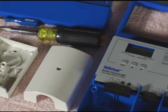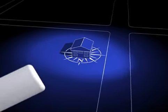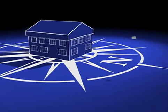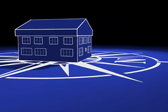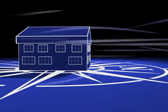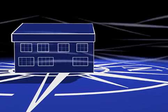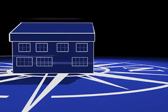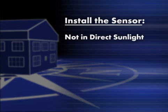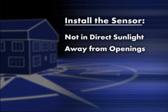Step 2. Install the outdoor sensor. The outdoor air sensor should be placed on an exterior north-facing wall, away from any potential source of heat. This will give the control the coldest ambient outdoor air temperature readings to ensure an adequate boiler target temperature. As a general rule, install the sensor where it will not be exposed to direct sunlight, away from window openings, dryer vents, exhaust vents, and boiler vents.